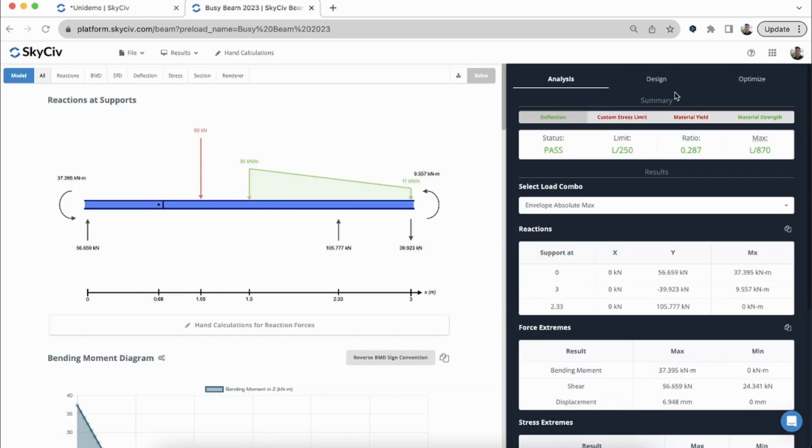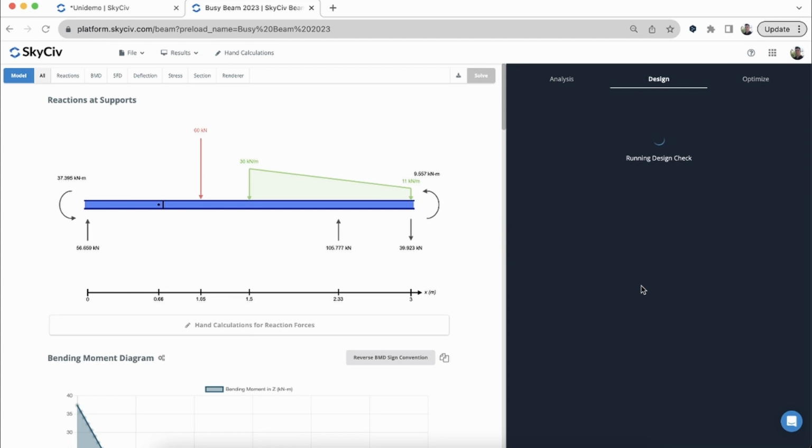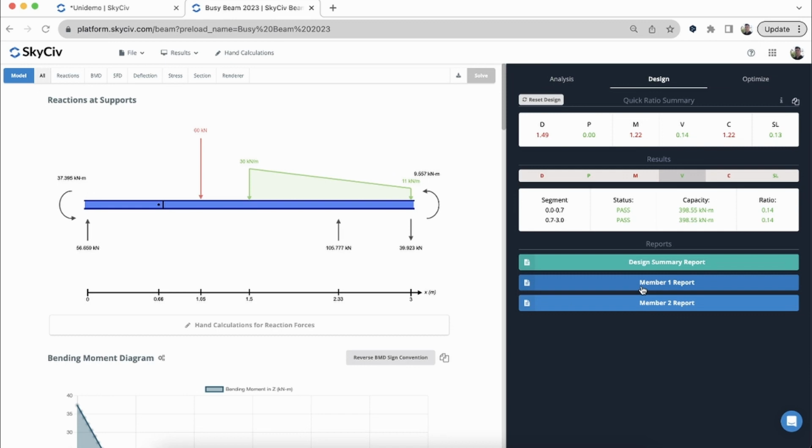And so now we're going to proceed with solving. So it's a very similar process to when we were doing the design for S3D. So we're just going to go through and run an analysis and perform a design check. Let's just see where we're at, whether the member is passing or failing. So we can see we've got a utility of around 1.5, so it is failing, and we have some moment forces it's failing on, some deflection, some combined design checks that it's failing, but overall looks about 1.5 the ratio.